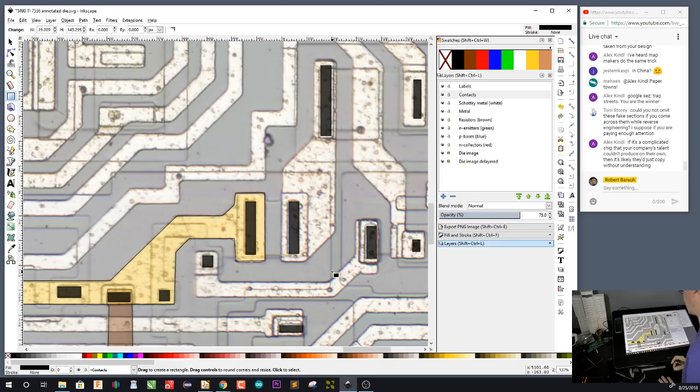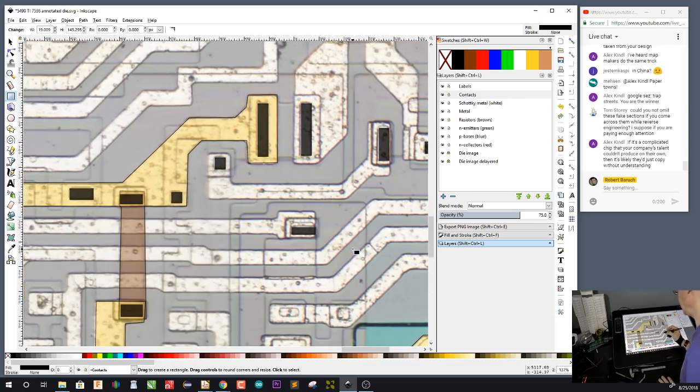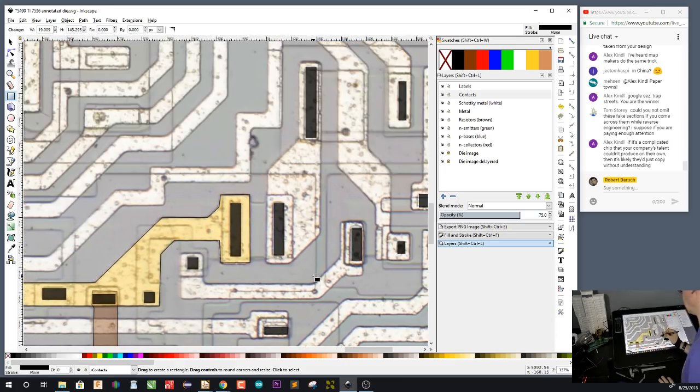So here's an interesting bit. We can see that there is some sort of resistor over here connecting this part of VCC to this part. I mean, there's nothing in between except this fat layer. So what's going on? It's definitely not part of a transistor. It's a jumper, but it's jumping nothing. So sometimes, as Freud said, a resistor is just a resistor.